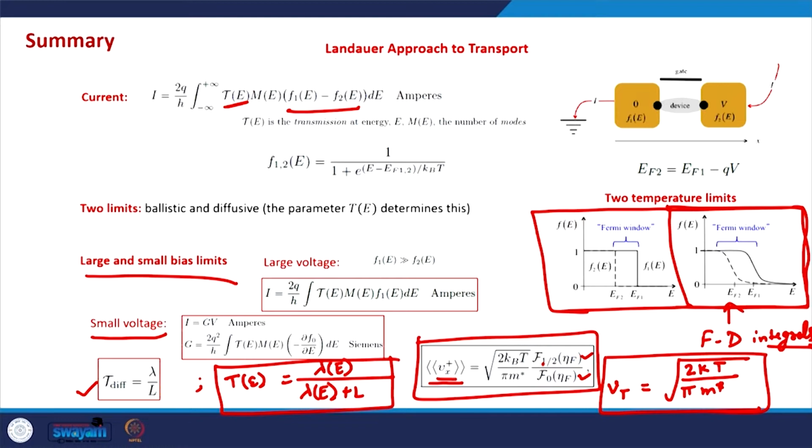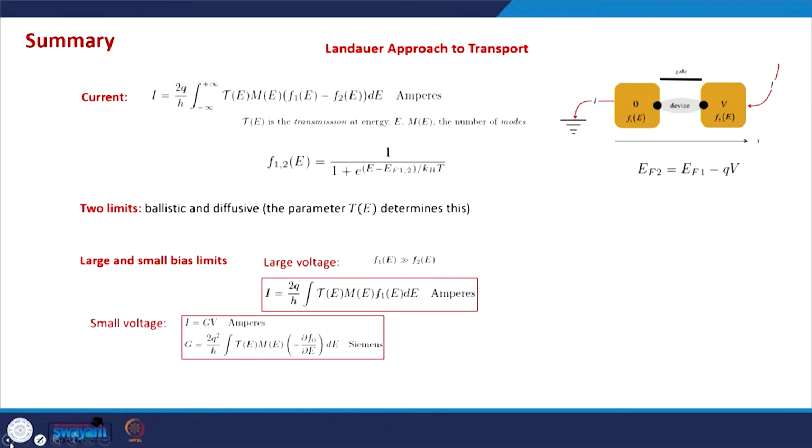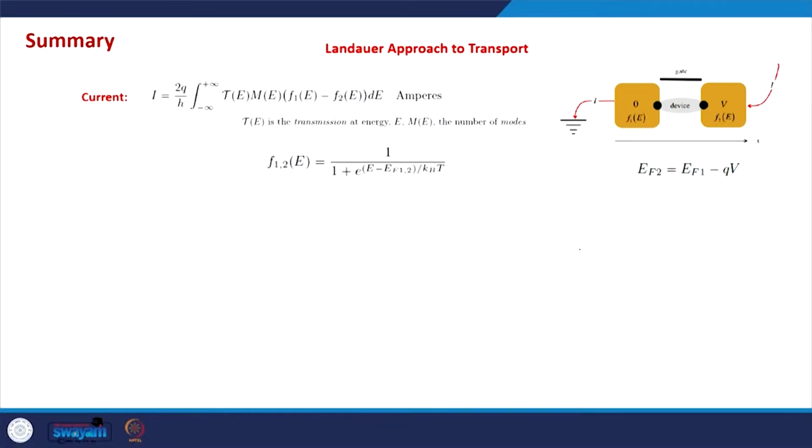So this is what we have, and this is also the situation below threshold in the MOSFET, because below threshold not much charge is there in the channel, which means that the non-degenerate semiconductor conditions are still maintained. And there is one interesting aspect here, which is that for the electrons sitting in the conduction band in the case of a non-degenerate semiconductor, it will look something like this.